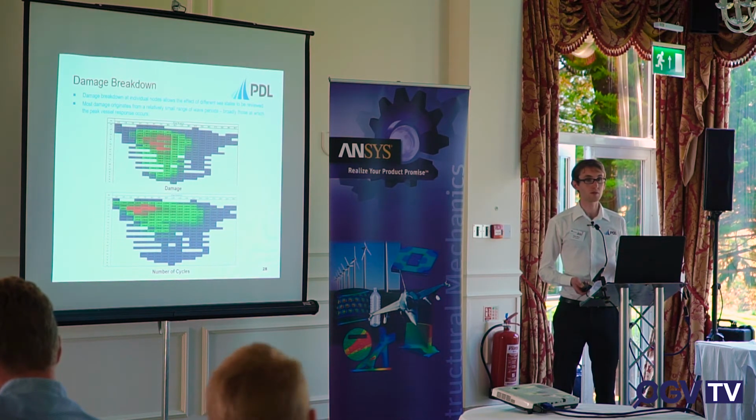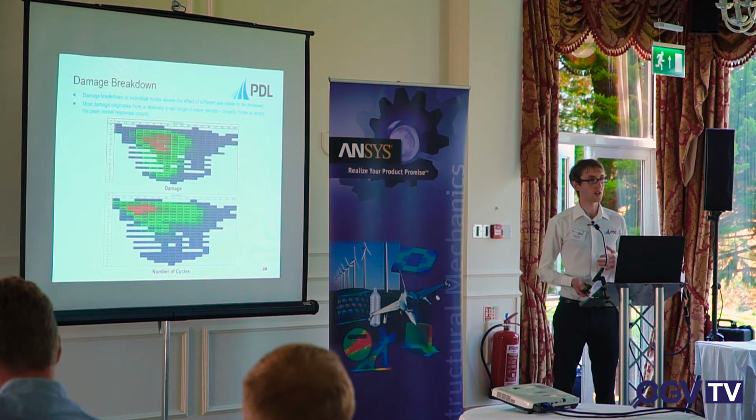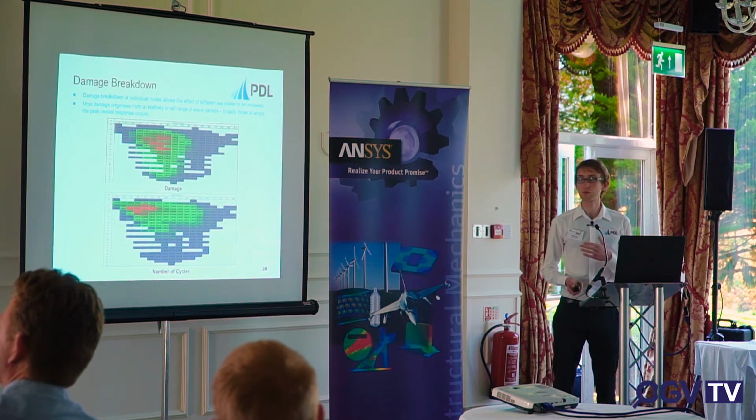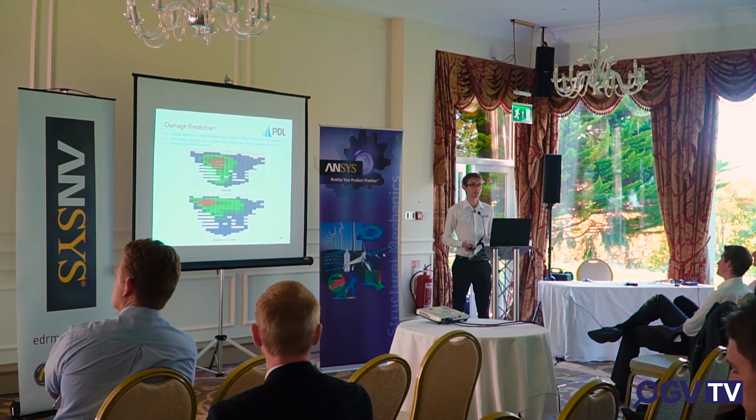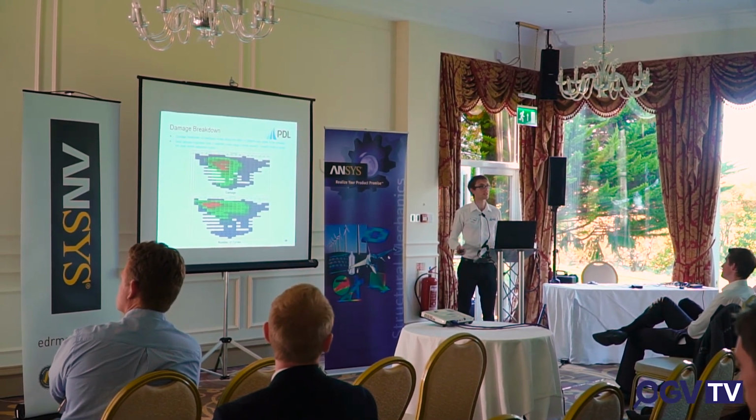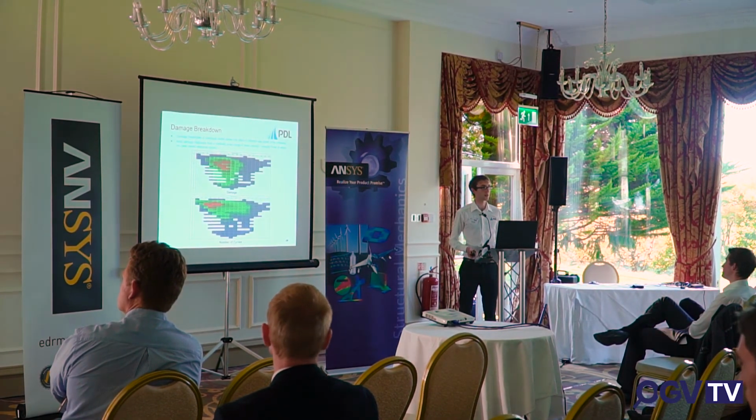Especially if you want to do some redesign because some bits are failing, or you want to pinpoint something. In this case, we pinpointed that the stowed condition is quite fatigue critical. So then maybe you want to do some different sea fastenings, for instance, that's going to support it better when it's stowed.